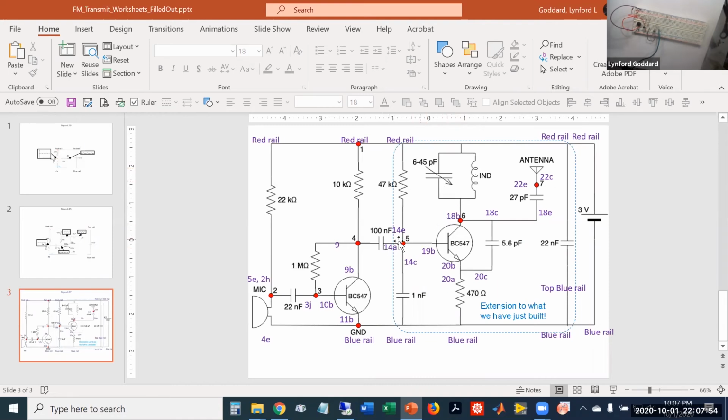Okay, so I think I mentioned this in the previous video, the functionality of this transistor. It's not serving to amplify. What it's serving to do is, the signal that we had coming into here is changing the charge that's in the base of this transistor, and it's changing what's known as the depletion width. So essentially, if I have current flowing into this and it's alternating as a function of time, then the capacitance of this element changes as a function of time.